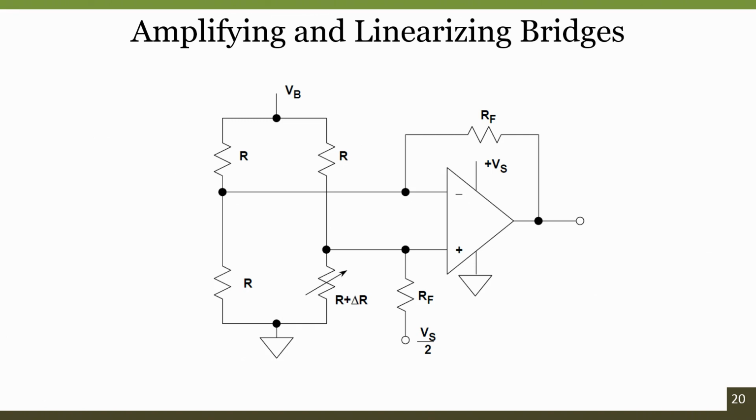So, that is one disadvantage of going with a difference amplifier, because as we discussed, the difference amplifier will have input resistances both on the negative terminal side as well as the positive terminal. Between the output from the previous stage and the input to the inverting or non-inverting terminal, it always contains an input resistance.